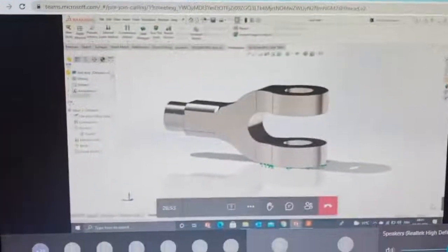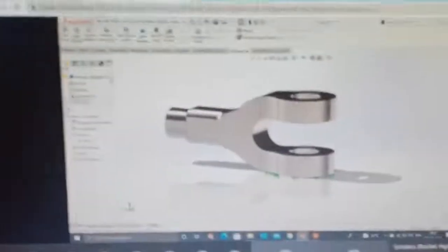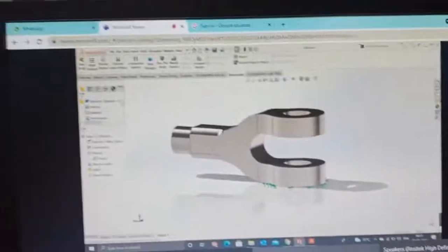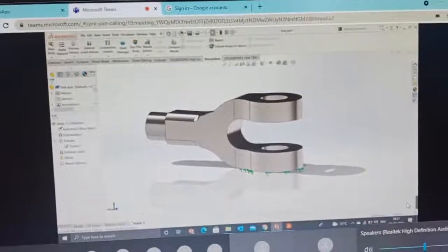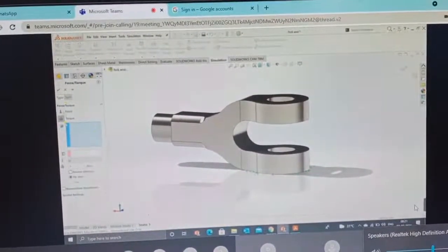or pressure. That means you can see, this part I am going to fix. That means it is going to be fixed. I am going to apply the external pressure from the top side, so that also I can do. You can see here, force. I am going to apply the force from the top side, so I just need to select the top face.